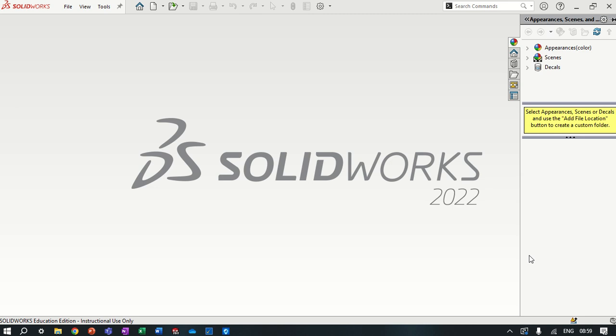When you open up SolidWorks 2022 or whatever year, there's loads of different versions of it, this is what you'll see. For the very first time, you will get a pop-up window that will ask you to set the units, and the drawing standards. Always choose millimeters, grams and seconds, MMGS. For the other one, choose ISO, International Standards. So millimeters, grams and seconds and ISO, choose those two.